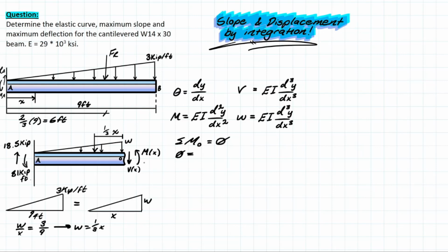First one is obviously the moment at x, or our point of reference. So that is going to be, based on our convention, positive. So we have a moment at x here. And then following that, we have to look at this resultant force. And this is broken up into a couple different terms. The first one being that it's 1/2, obviously, for a triangular distribution.